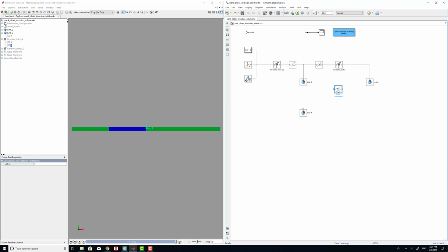Click OK. And then you can put it on top of the line. So the thing is, when you're doing coordinate transformation, you have to pay attention to the B and F of the rigid transform. When you connect B and F in this way, that means you always want to move the target that is connected to your follower by the amount of transform you defined.